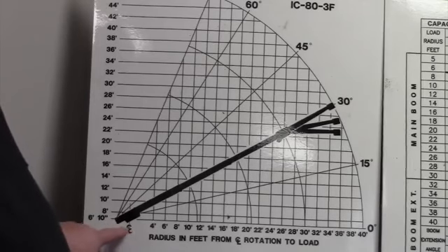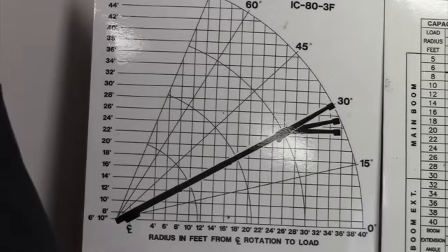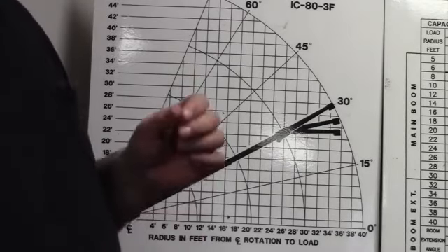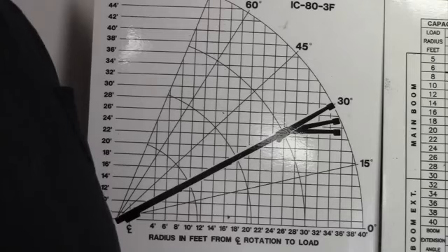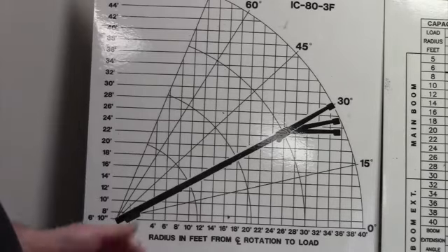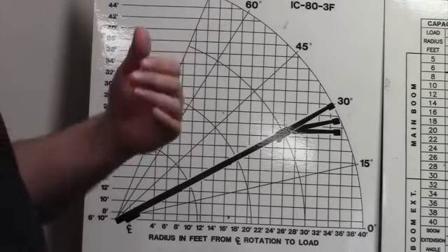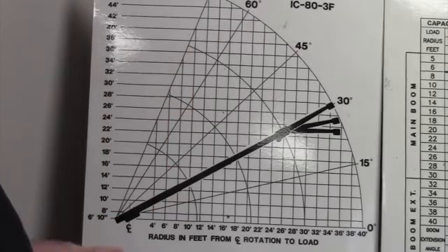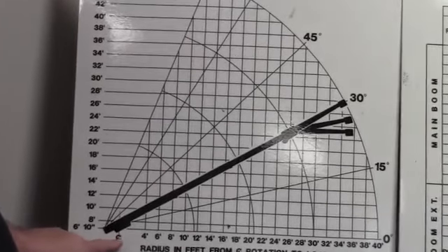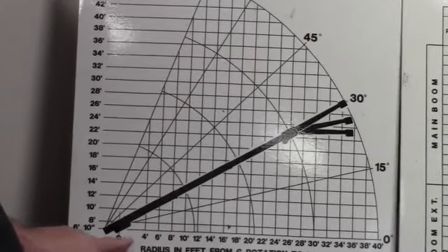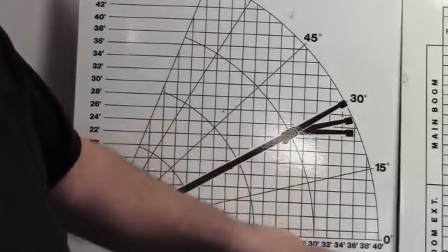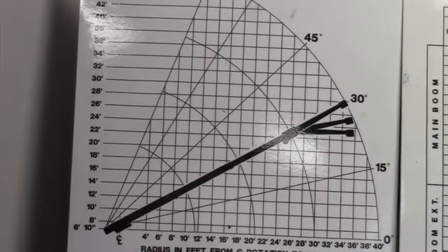If you look here, you'll see the center line is somewhere forward of the boom pivot pin, which on this particular crane happens to be the exact center line of the turret where the boom rotates. And so we can use the load chart to calculate our load radius. Once again, the load radius is the distance between the center line of the crane and wherever your hook happens to be hanging at that particular moment.